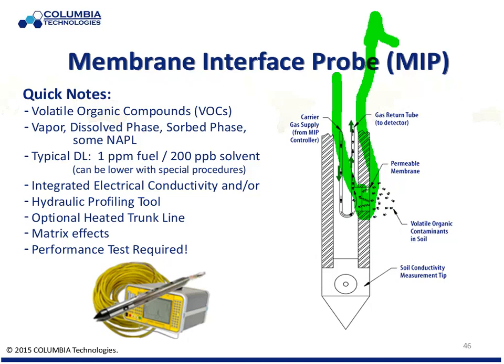That protocol per the ASTM is to essentially push for 1 foot, heat the zone for, let's just say 45 seconds, push for 1 foot, heat the zone for 45 seconds. If you do that consistently, then the variability of the subsurface will be the primary factor leading to the data curves that you're looking at. So if you've heated the material, you create a partial pressure there, you've got a lower partial pressure on the other side of the membrane, and so you get basically transport across the membrane from outside to the inside of the inert gases, goes up to the surface, and it sweeps past a series of detectors.